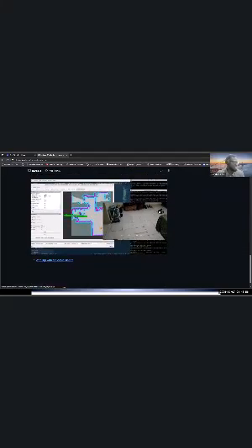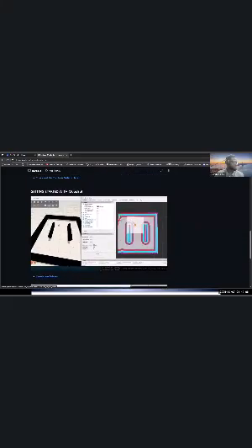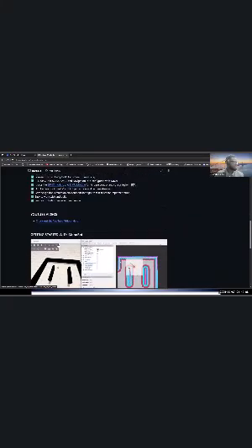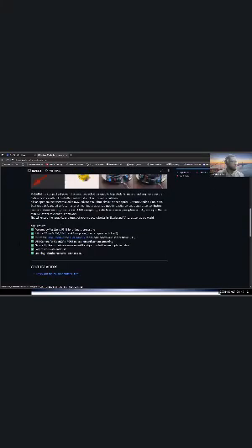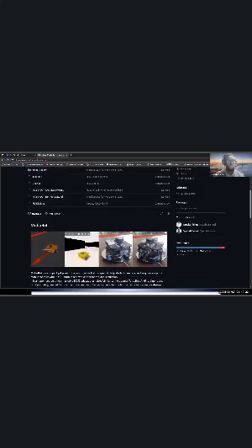So this is the mobile bot in action. It's going to navigate autonomously. You can actually do this in your room, and this is a room somewhere in Nigeria. It can do SLAM and navigation, working with the actual robot. For simulation, there are some videos to support you. You can check some of the YouTube videos it works on. It's powered by Raspberry Pi, RPLiDAR C1, USB camera, OpenCV, and there's an IMU as well. The good thing about this is we built the IMU and also the motor driver. The branches are Humble.